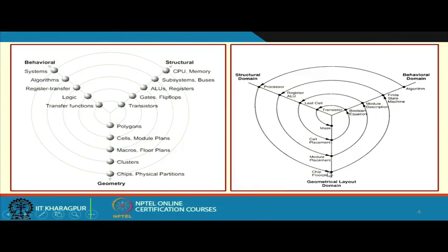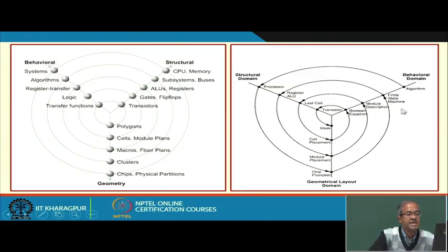Now, from here again you follow this path. This says finite state machines, not only finite state machines, it can be some kind of logic specifications also. So, for each of these blocks you again go to the behavioral domain and specify what these blocks actually try to perform. What is the functionality of the CPU, what is the functionality of the memory and so on. And each of these again you will be traversing this path, this synthesis, translating them into processors, ALUs, registers, etc. Register, ALU, multiplexer. From here again you will go to placement of the modules, refining the placement. Again you go to the description of the modules. Again you go to descriptions like gates or some cells, as we will talk about later. Then again how to place these cells, then again low level, finally transistor up to the layout mask.